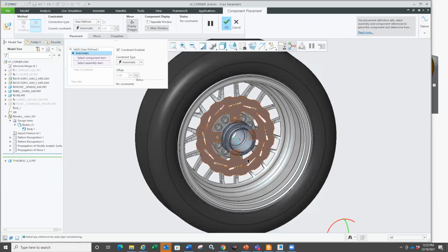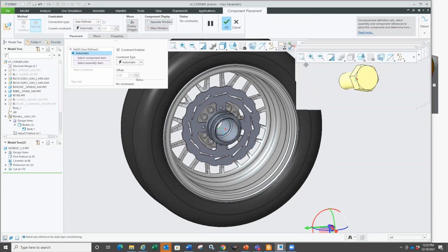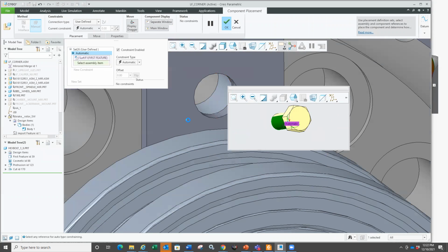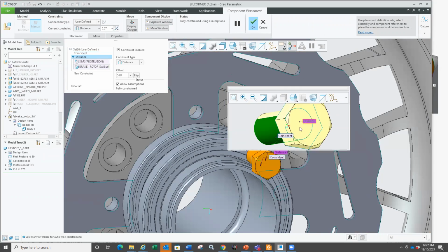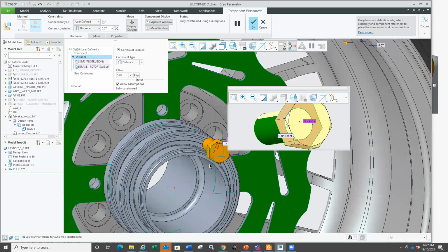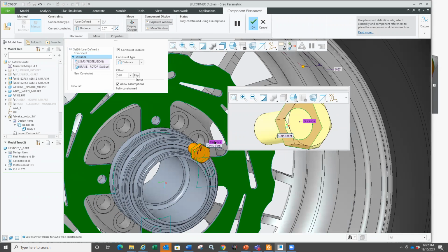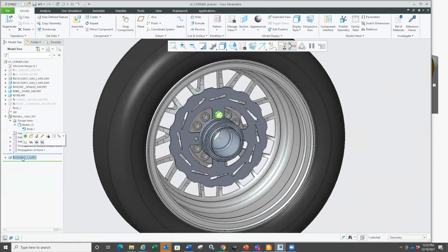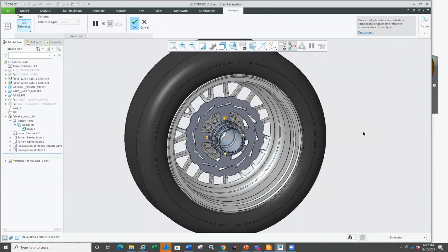So I probably want to go to separate windows. It's just easier to assemble it, right? So I can just pick some geometries in here. This is where I talk about cross-platform design intent, where I'm essentially constraining a Creo model to a SolidWorks geometry. And now I should be able to set that to coincident, just applying regular constraints. And now I should be able to just pattern it, and it should pick up the reference pattern just like you would have done in Creo, right?